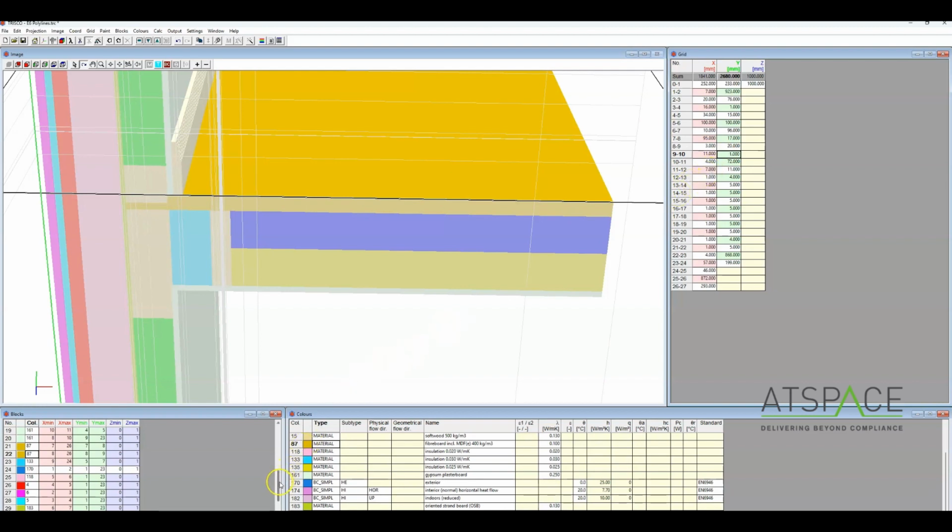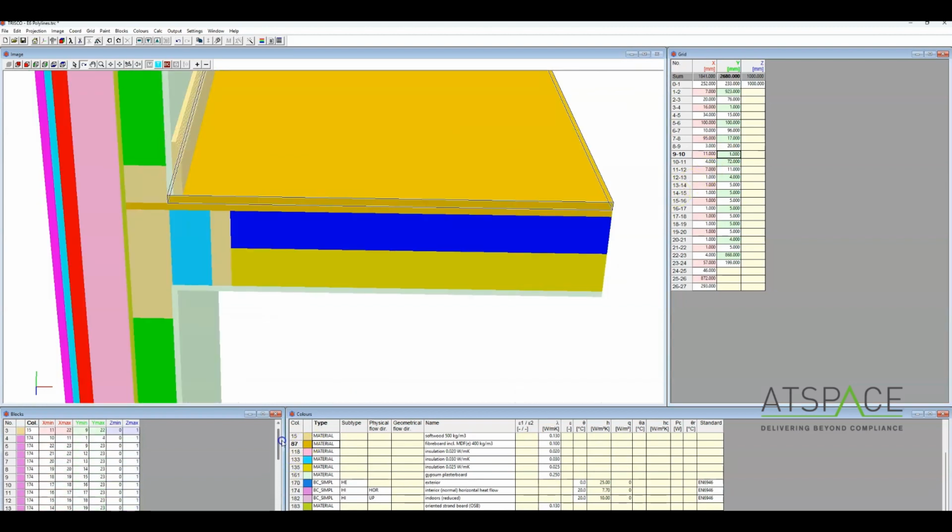So now we need to put in a new block for that boundary condition, and it's the same hierarchy as before in terms of importance and overlapping other blocks. So with boundary conditions, I'm going to put it at the top. So I'm going to click on the top one that's already in the model, and up here we've got those two arrows which you remember from before, but this time instead of moving blocks around, they're for inserting blocks, and you can use them also to insert grid sections if you wanted to create a new grid section rather than splitting one out.